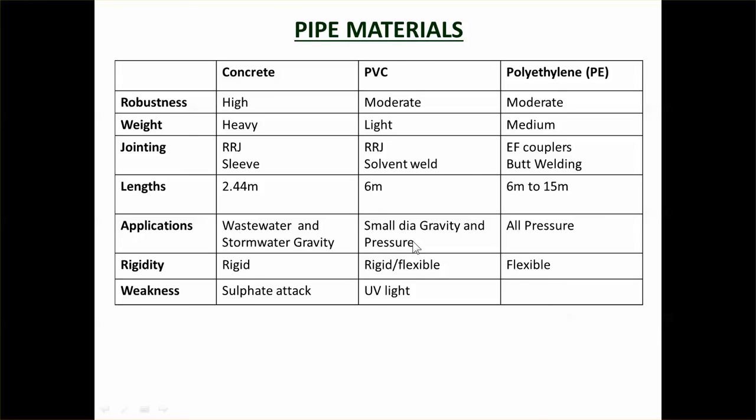The reason why it's no good when it gets bigger is because it's a plastic pipe. As it gets bigger, it gets more liable to be crushed into an egg shape by surface loads. So as it gets bigger, it has to get much thicker wall to be able to resist those surface loads, and it starts becoming more expensive than what a concrete pipeline would be.